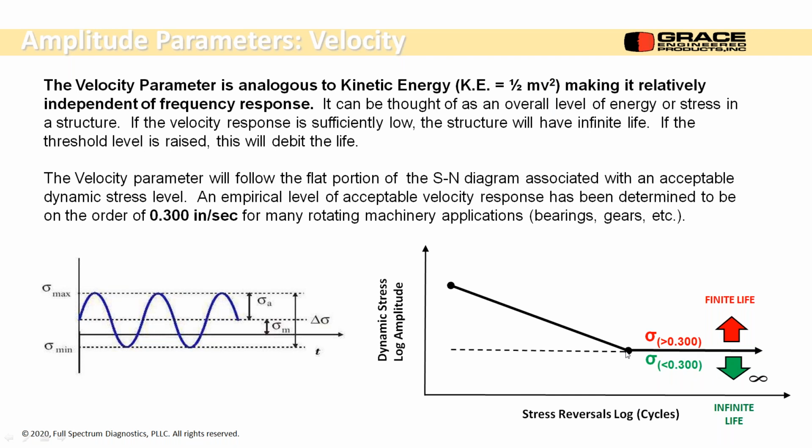I look at just a threshold level. Okay? It makes it so much simpler. It's easy to do. You don't want to be calculating an allowable displacement for every number that comes through. You just go with the velocity, kinetic energy related alarm value, and you get great results.